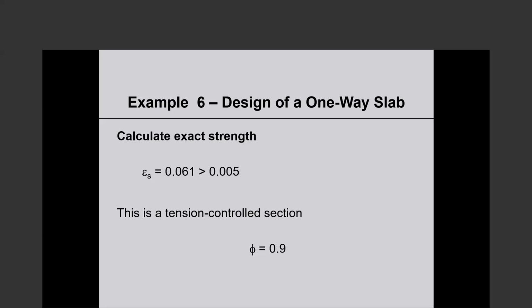Let us say you targeted concrete strength of 4,000 psi and it didn't come up to 4,000 psi. It was 3,700. So let me try to understand. That made the beam over-reinforced. You are going by the old rule of 3/4 of rho balanced, and the rho balanced changed. I'm just trying to understand.